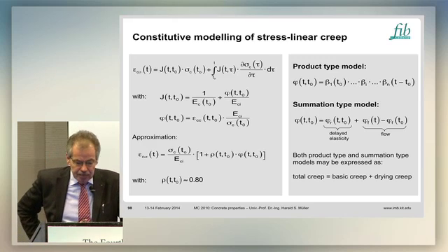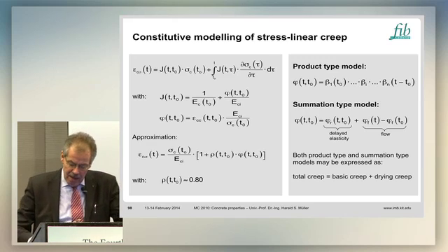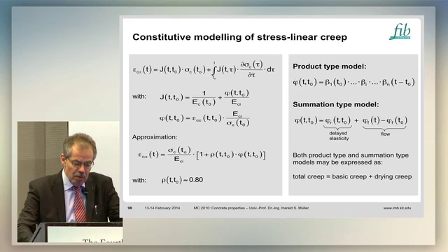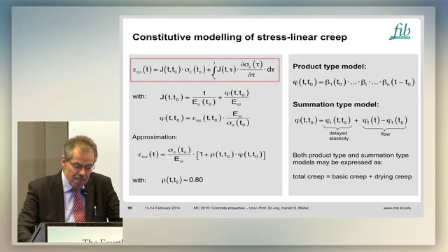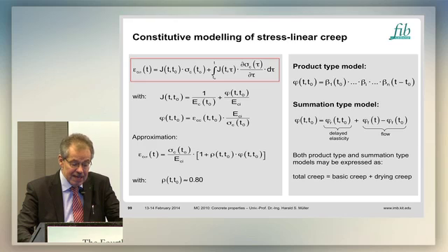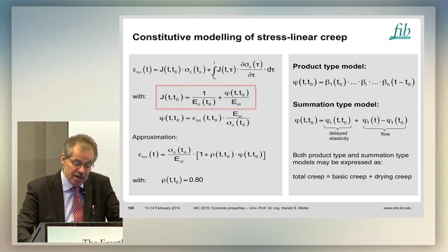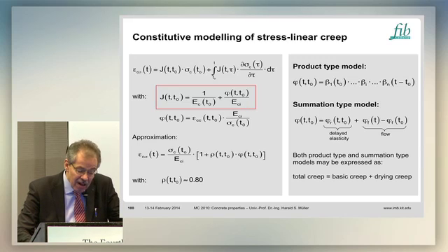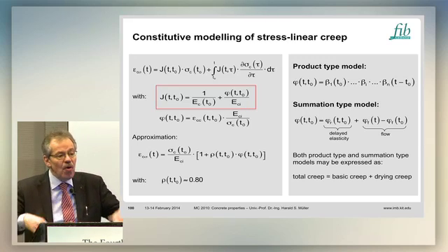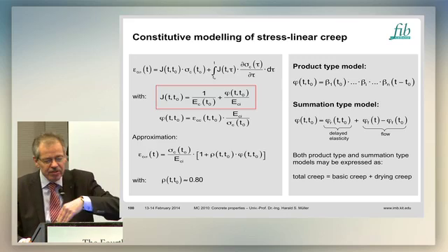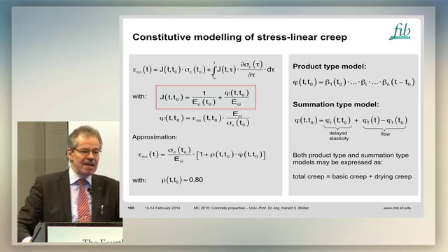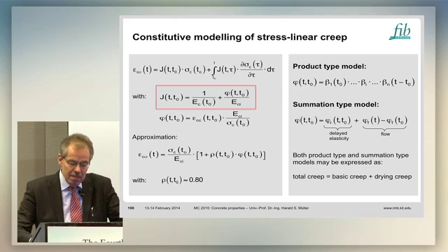Constitutive modeling of stress linear creep. I already mentioned various types of approaches. When accepting linearity, this basic Volterra equation is valid. We have our definition of the creep function, reflecting creep coefficient and modulus of elasticity. And we can develop from this equation an algebraic equation according to Trost's procedure, which was finally a little bit refined by Bažant, but it is the same equation.